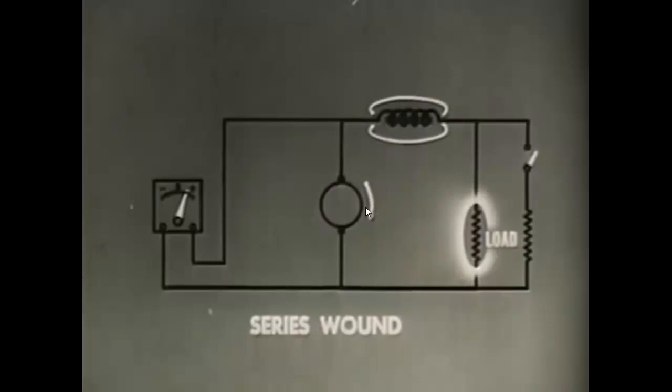Now, as the rotor turns, this is something that is forgotten a lot of the time. As the rotor turns, the rotor's magnetic field must always oppose. If it doesn't oppose, you can't generate energy. I've had this discussion with a few people. Voltage at least comes from the change in magnetic field, and then current is the opposition of magnetic fields.